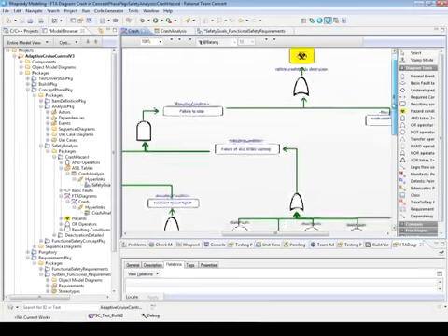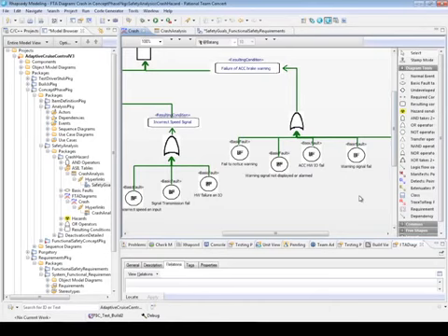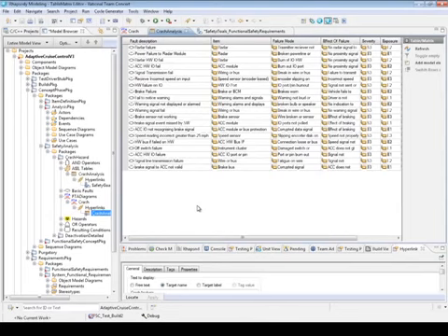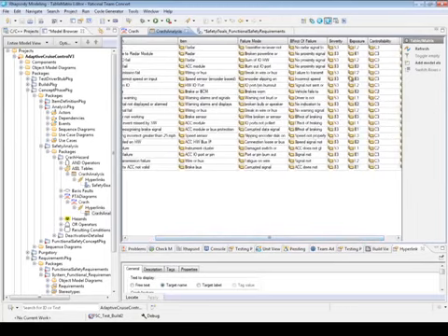By using the relevant AND or OR gates and the resulting conditions, this can drive out a set of basic faults in the system. To aid in automotive safety analysis, the safety analysis profile has been extended to cover specific safety analysis requirements for automotive. One example of this additional functionality is a table that behaves like a failure mode effects table, looking at the fault description, the item that it affects, the failure mode, the effect of the failure. But in this instance, it also covers the inputs, the severity, exposure and controllability, which are used to determine the ASIL.